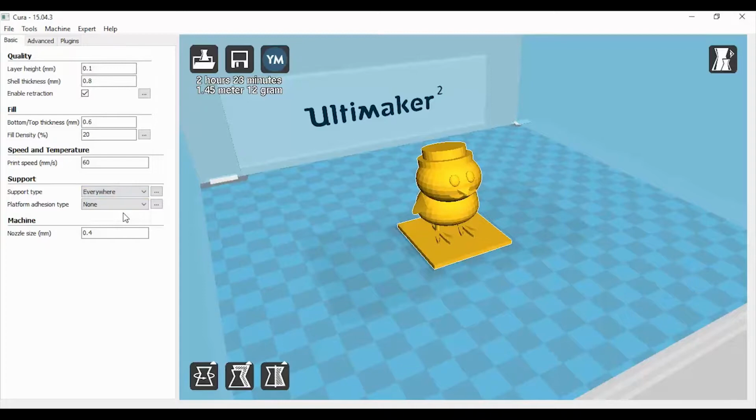when selected, the option of touching the build plate will only use support material that travels from the part to the build plate itself, whereas the other setting, everywhere, will involve putting support material from one area of the part to another area of the part. This is important to consider when debating how fragile portions of your part will be, as well as when considering the surface finish that will result after removing breakaway support material.